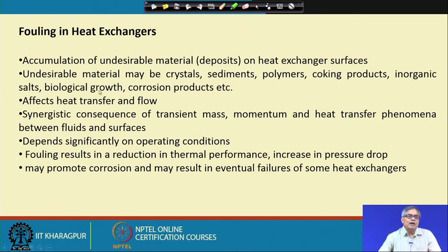The undesirable material may be crystals, sediments, polymers, coking products, inorganic salts, biological growth, corrosion products, etc. So, you see, due to the physical and chemical changes of the fluid, due to the interaction between the fluid and the heat transfer surface, which will again be augmented by the presence of flow and heat transfer, there could be different kinds of deposits.